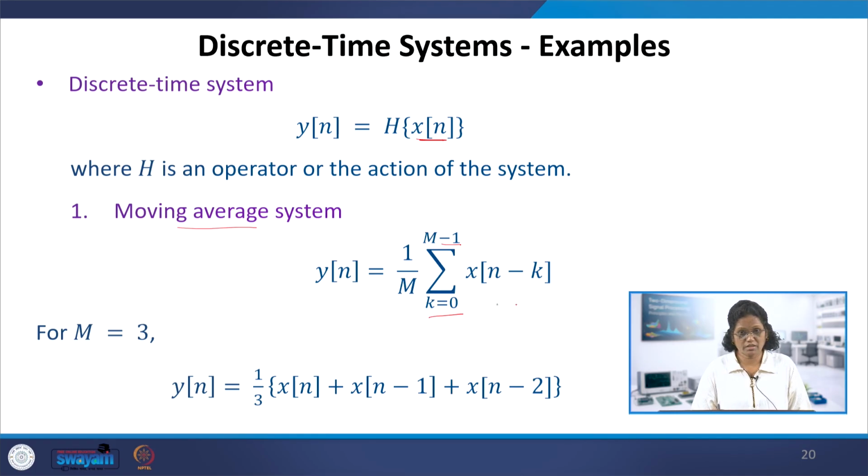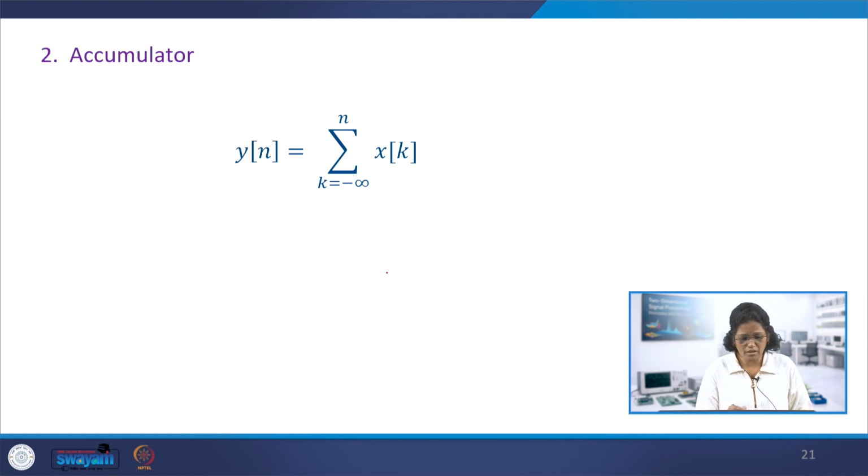So similarly, this can be of any window length. And the accumulator, so you want to accumulate the signal values which are coming in for a certain time, and then do the processing. Okay, so this is going to be the accumulator y of n, where k is varying from minus infinity to n. There are 2 representations of this accumulator x of k, where the time, suppose minus infinity, in the sense minus 5 for example, to the present instant n. So how do we write this?